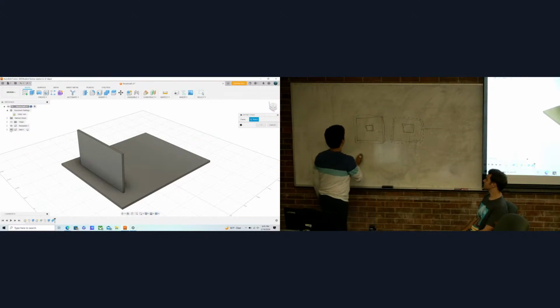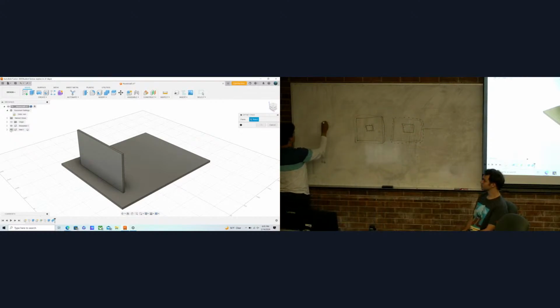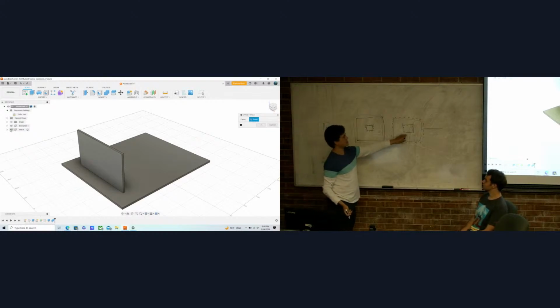And the reason is, moving over here, if I have a block like this and I laser cut through it, the laser is removing a section of material that actually has width. It's not cutting these pieces in two where this plus this is the full width. There's a section of material that gets removed, turned to ash, basically. So when you're using laser cutting, your holes end up being bigger than what you had in CAD.